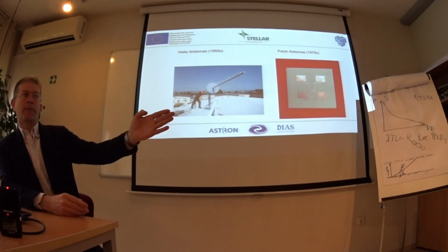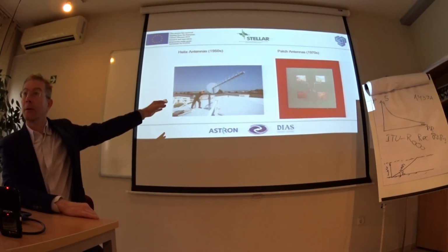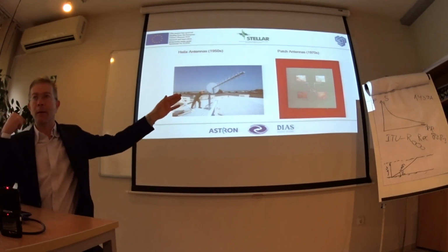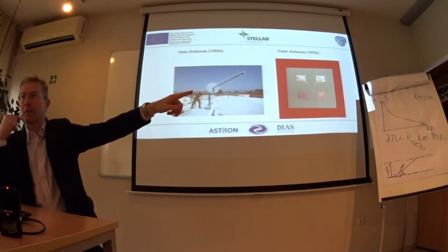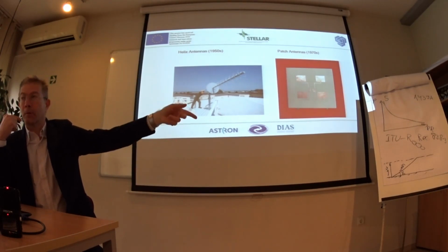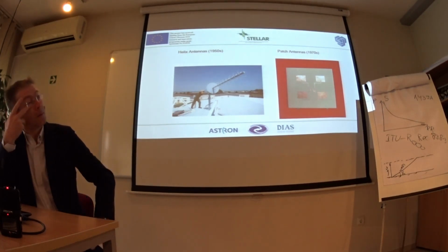If you look from behind the antenna, exactly like this, this is how the sense of polarization is determined. You stand behind the antenna and watch toward the propagation direction. If it turns clockwise, it's called right hand. If it turns counterclockwise, it is called left hand circular polarization.